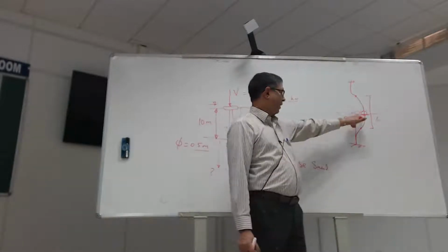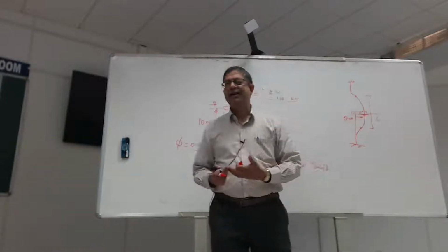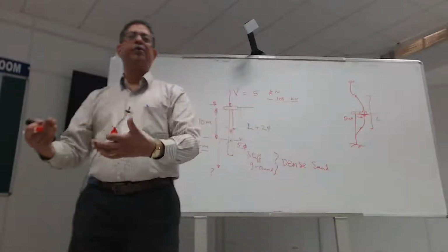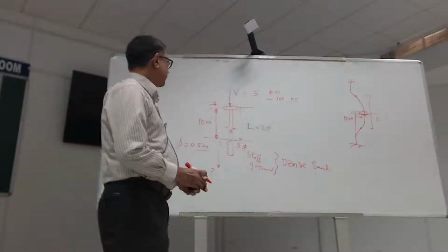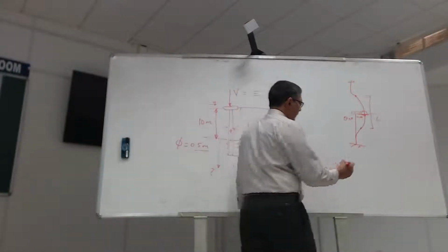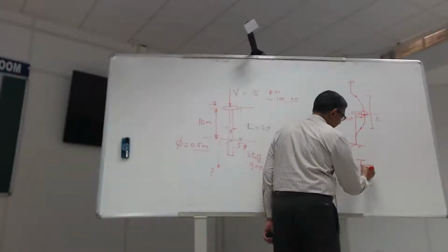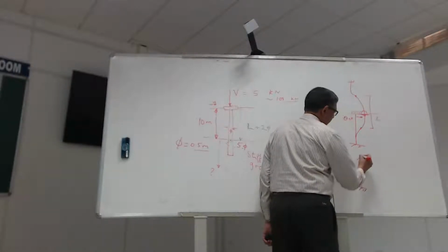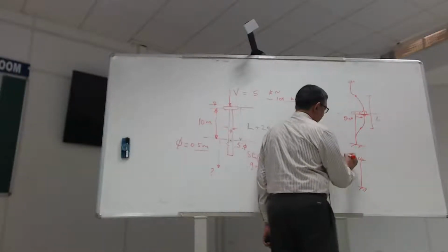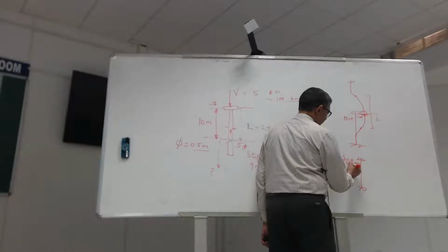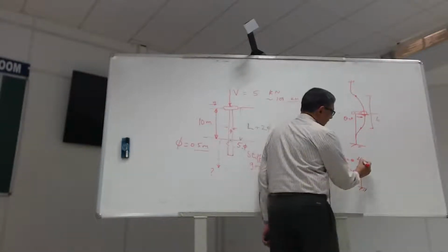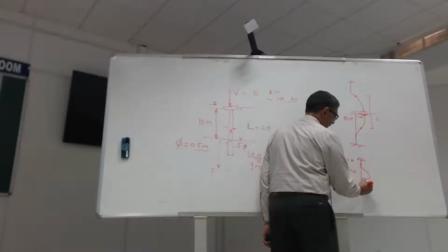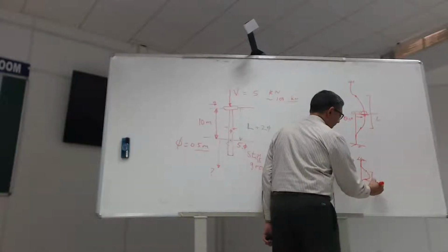So you need to be aware of what restriction you are imposing onto your structure, in this case the pile cap. If I fix everything like a strut, so delta is 0 and theta is 0, the only thing the pile can do is that, right? So my effective length will be L1.